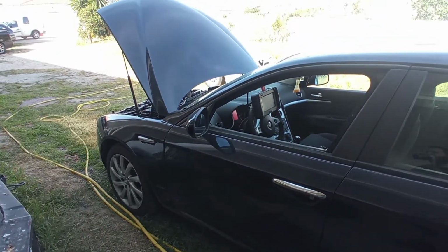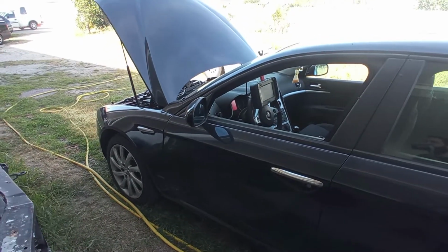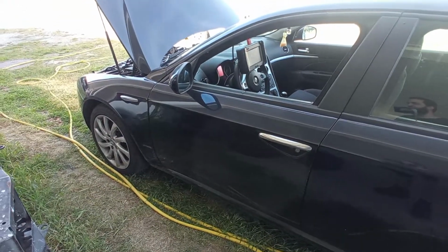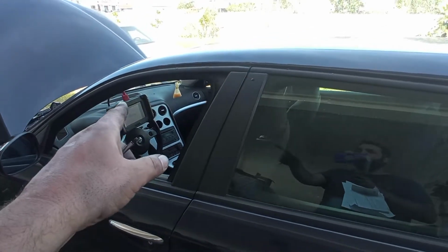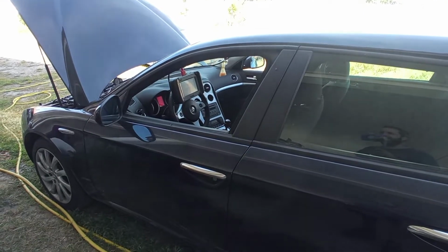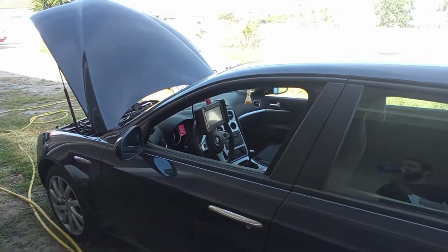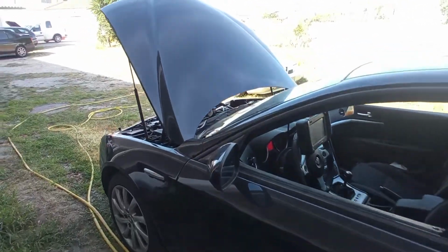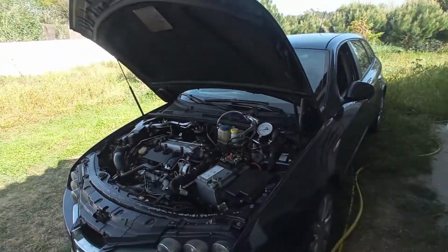That's why the intake valve, the throttle body, does not work. That's why I have no back pressure, because the DPF probably is not there. I have to check that out. But what led me to be mistaken was that on the parameters, I have all of the pressures as they were supposed to be. That's why the pressures were so good, just perfect. And I thought it was because of the exhaust leaks. But in fact it was a badly done remap.